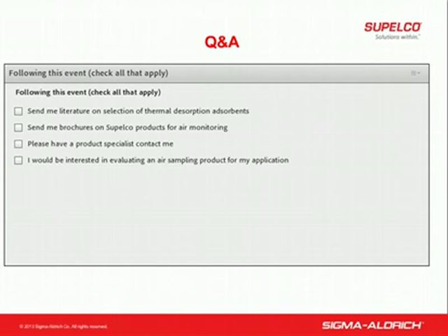Okay, and the next question is, what adsorbents can trap the broadest range of compounds? Today, of course, Tenax is very good at trapping the midpoint boiling point compounds. The Carbopack X is doing a very good job of trapping the mid-range, but when we get to some heavy molecular weight compounds, they can be a little strongly adsorbed there. Some of the weaker Carbopacks do a pretty good job with a broad range of compounds, but they don't do a very good job when the compound is a gas at room temperature.